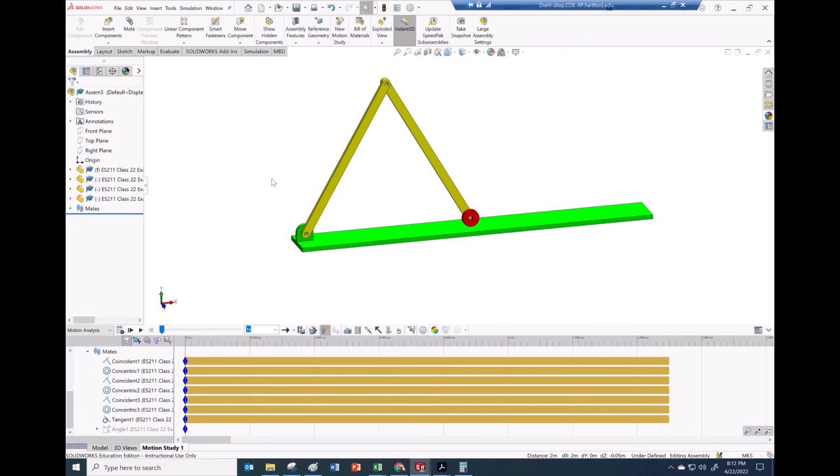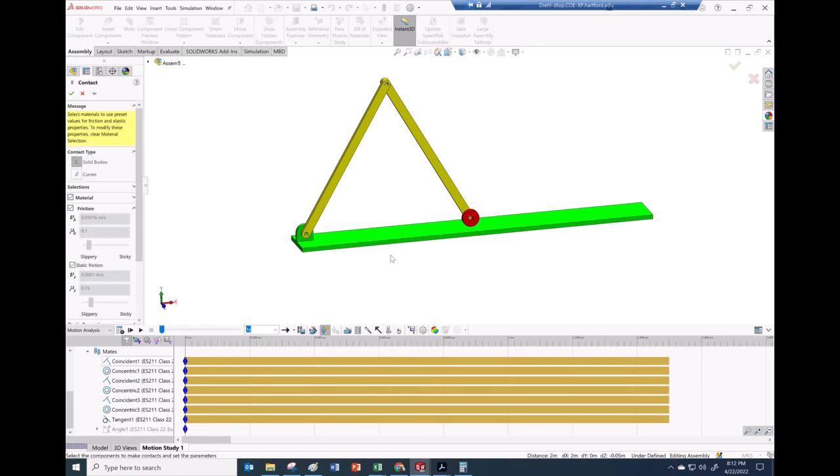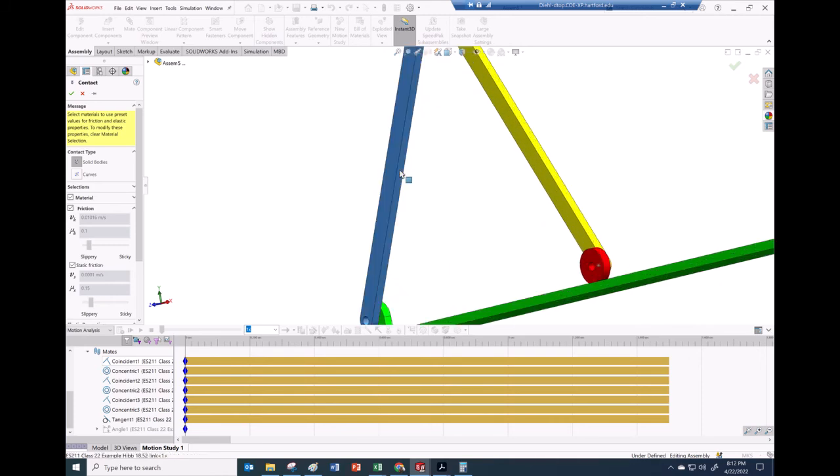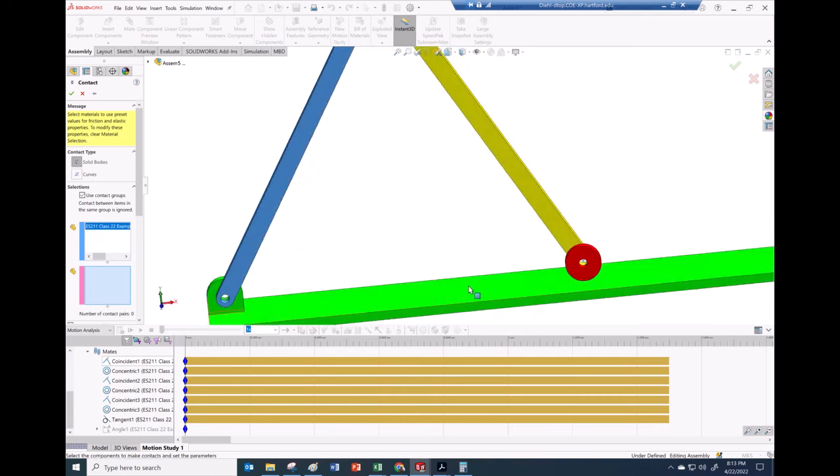And I'm looking for other things. Okay, the 1.5 seconds is enough, I had found out, for this thing to go to horizontal, but I want it to not pass through the piece. So I'm going to go ahead and make contact groups. Well, first off, I'll change my selection thing and use contact groups like that, right? I like to hit that contact groups. And I'll have a contact group between this and that. All right.